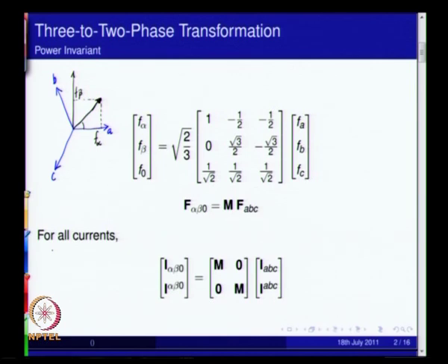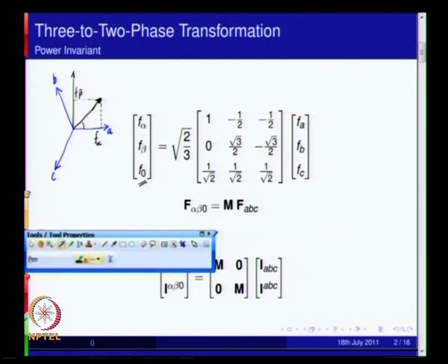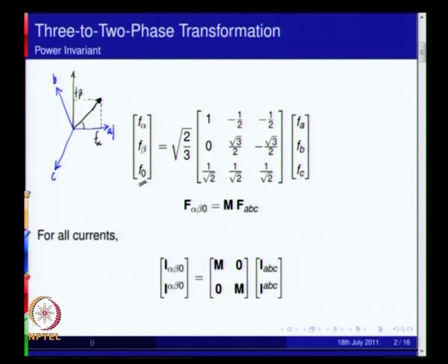And then because of requirements of inversion and seeing what additional information was missed out, we then added the F0 component as well, which is a representative of the zero sequence component of the excitation or of the MMF. So we have in this manner succeeded in splitting or in representing the three phase MMF in terms of two phases. In other words, what we are saying is that instead of three excitation terms which are caused by an